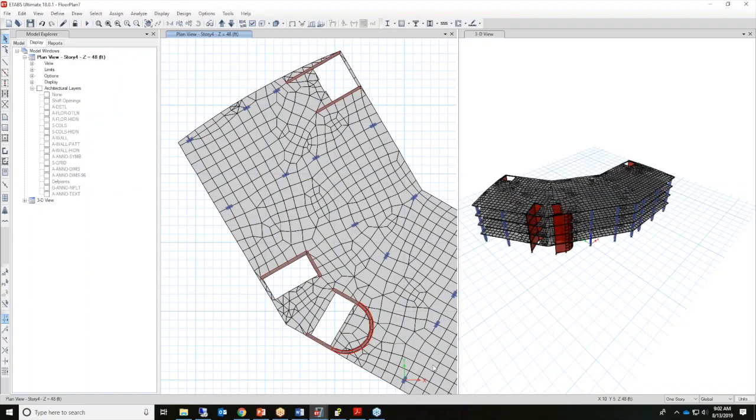Okay, so just a quick overview. So what is meshing? A mesh is a network of line elements and interconnecting nodes used to model a structural system and numerically solve its simulated behavior under applied loading. In object-based modeling environments, engineers can generate structural models by drawing area objects that physically define the structure itself, such as wall panels, floors, and/or ramps.